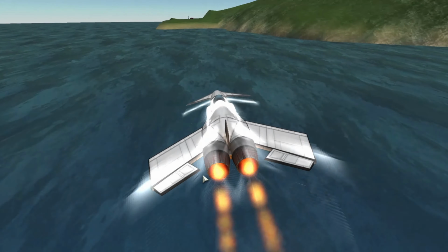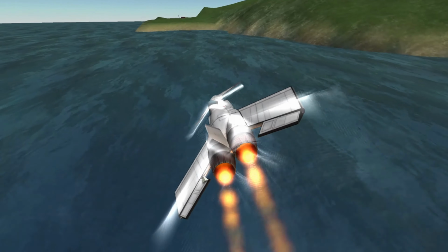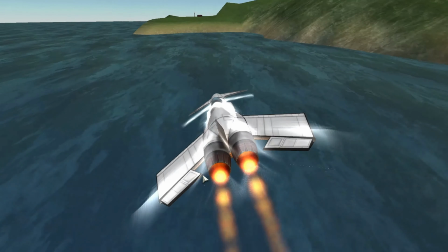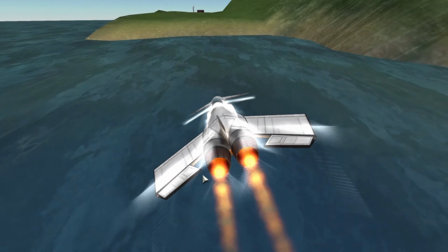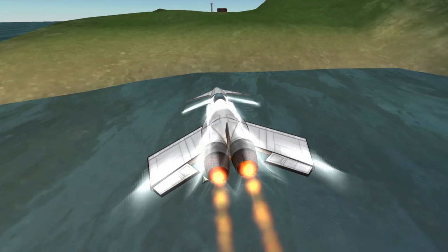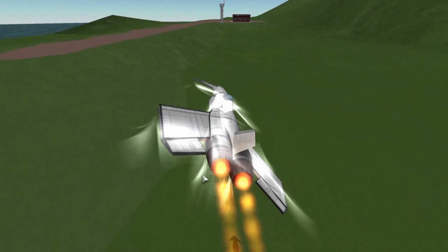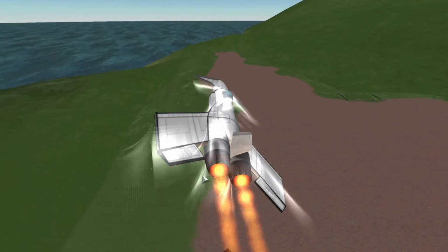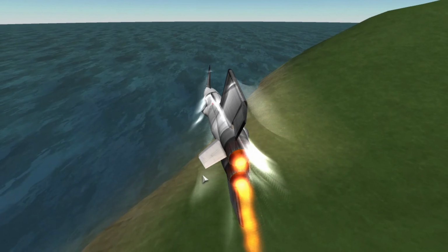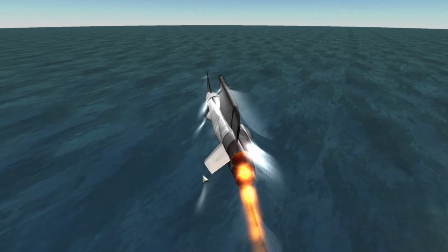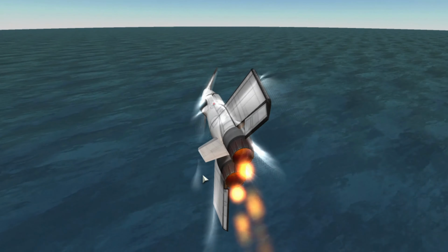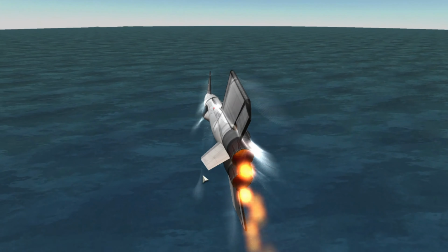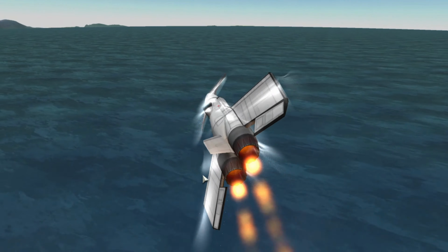Swept wings are usually used to fix this problem because when air travels over a swept wing, the chordwise flow travels perpendicular to the leading edge of the wing, and the spanwise flow travels down the length of the wing. Because the air is divided when it travels over a swept wing, less air will be accelerated, so higher speeds are needed to reach the critical Mach number. However, the spanwise flow adds up throughout the length of the wing, so that there is more spanwise flow at the tip of the wing than at the base.